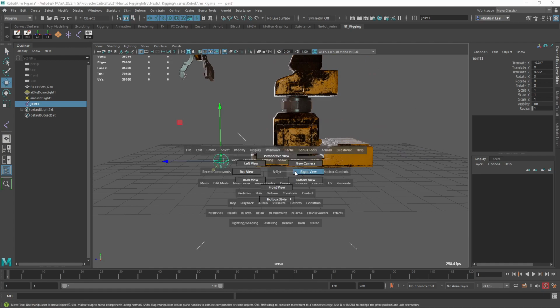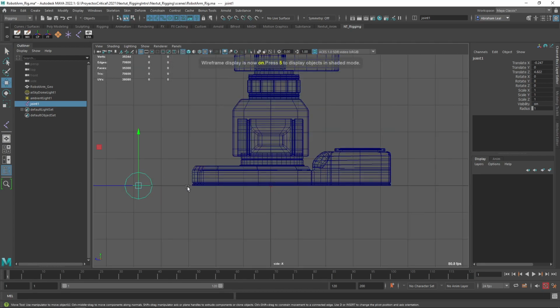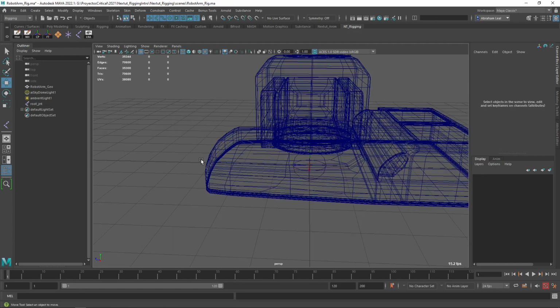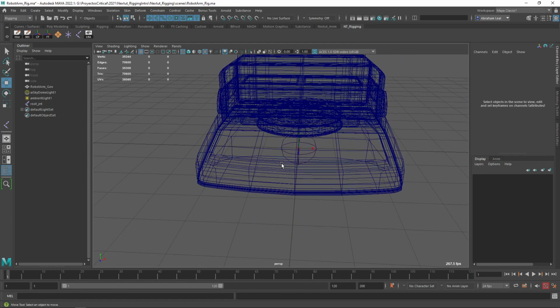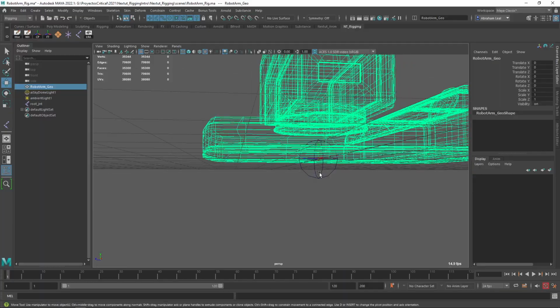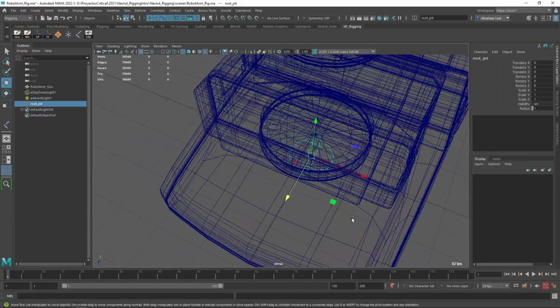So this joint right here, I'm gonna go right view. And we're going to snap it with X to the center of the grid. That's going to be my root joint. And I'm actually going to zero it out so that it's perfectly flat on the ground. And I'm going to call this root underscore GNT because that's the root joint. And this root joint, we don't need to change its local rotation axis. I'm going to turn it on just to see it because it's very common that the root joint is oriented exactly the same way as the world, because it's very common to just grab this guy and move it around. So we're gonna leave that one just like that.